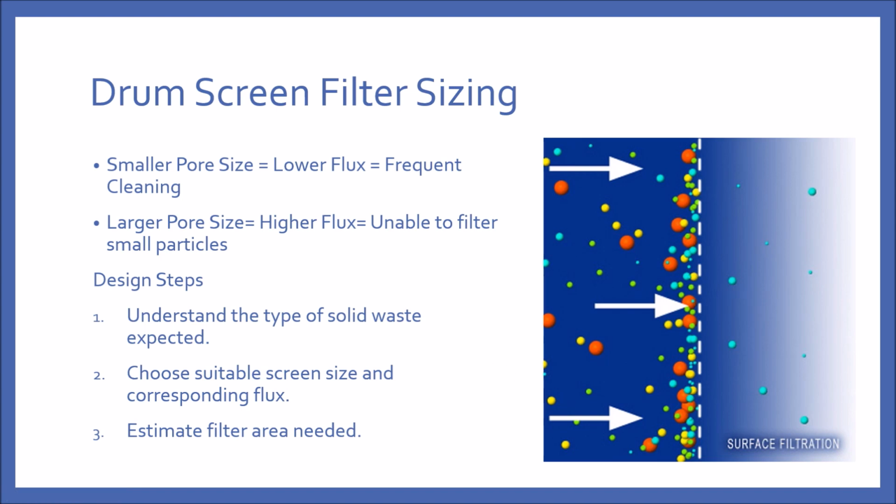Drum filters are commonly used in the aquaculture industry, especially in the fish industry in a saltwater process. However, do note that a drum filter is usually more expensive as compared to the traditional media filter. There have been debates on the benefits and cons of using drum filters. One of the cons with formulated feed is that it sometimes tends to disintegrate when it is rotating in the drum, further aggravating your suspended solid issue.